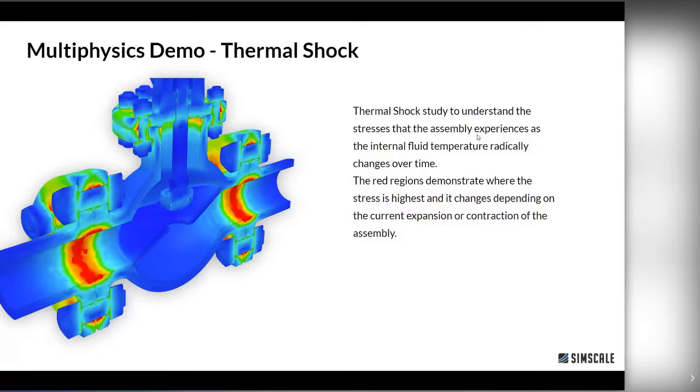Then we can take a look at the thermal shock analysis. So this is where we are not looking at the fluid now, but where we are using the original CAD to apply a changing thermal load to the structure to see what happens internally. And we really want to know, do any of the components reach the yield stress, and is it going to be safe? And that will give us a good indication of what the lifetime of the valve would be.